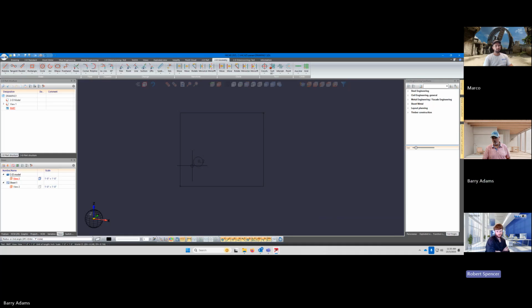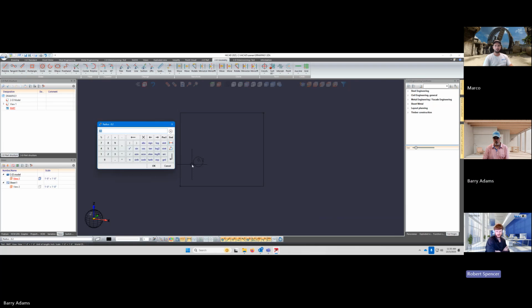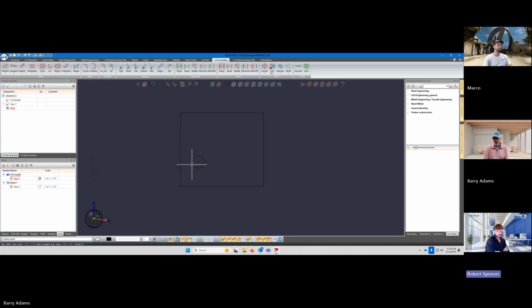Okay. So now we want to just key in a value for this circle. So again, remember what you did with the rectangle? You hit spacebar here. A couple of these little fundamentals, once you get them down, then it goes a little smoother from here. Now notice that it's asking for a radius. In 3D, it does not necessarily do that. So in 2D here, it asks for a radius. So we just need to say this is a 1/2 inch hole, so we need to give it a 1/4 inch input here. And then OK or enter.